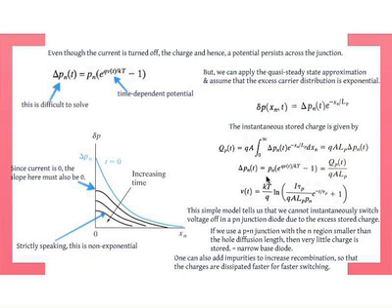Now, this also tells you that the excess carriers is now related to the charge divided by QA times the diffusion length, which is also intuitive if you think about it, because A times the diffusion length is the average volume that these carriers exist in. And Q is just the electronic charge. So total charge divided by Q is just the number of carriers. Number of carriers divided by the average volume they exist in is the average concentration. Yeah, so it kind of makes intuitive sense. Although, I'm hand-waving here a little bit because we made this assumption of this exponential.